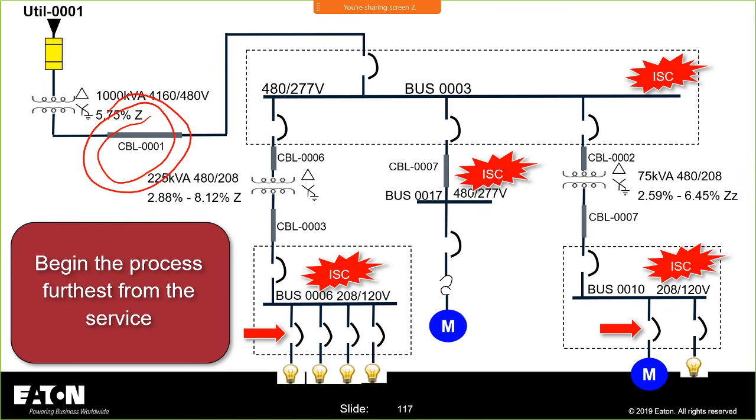You can, if you know that you're going to have a panel that's on one side of a complex as opposed to the source being on the other side of the complex, you don't have to use 20 feet or 15 feet. You can use 100 feet as long as you know it's not going to get shorter than that, because when you're using breakers, if the fault current goes up, you're in a world of hurt, and you didn't plan for it. So assume a smaller, shorter, reasonable length on all of these. Your ability to estimate these lengths more accurately than your competition will give you a better quote on your jobs. So you're going to want to make sure you navigate around these lengths of these conductors.